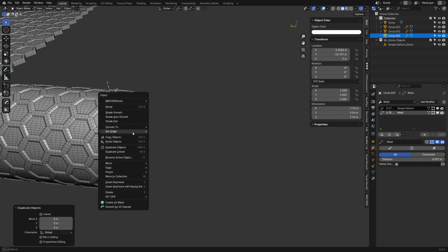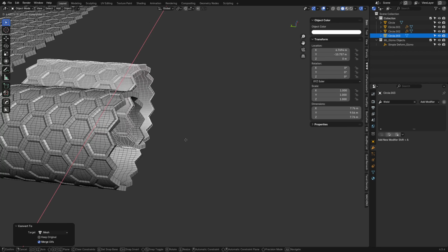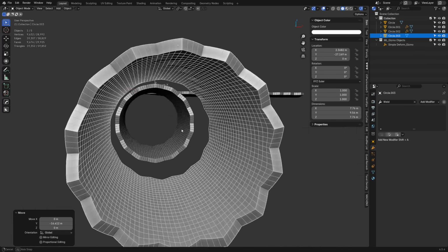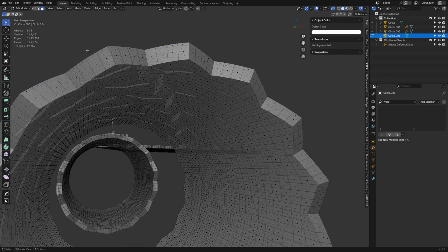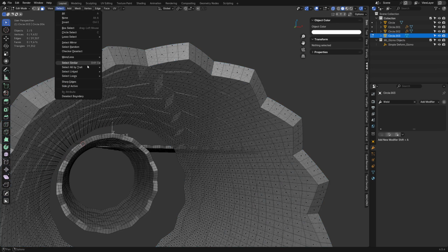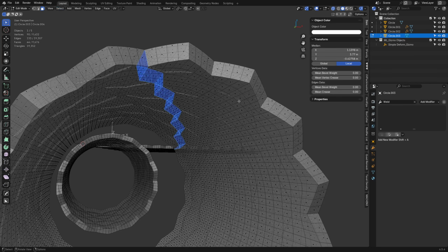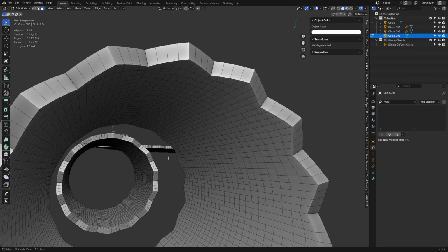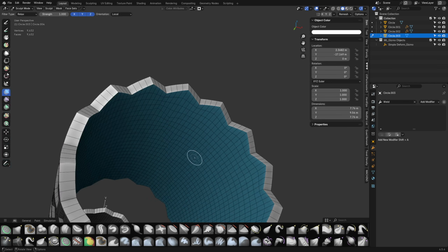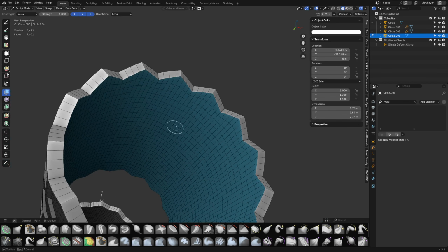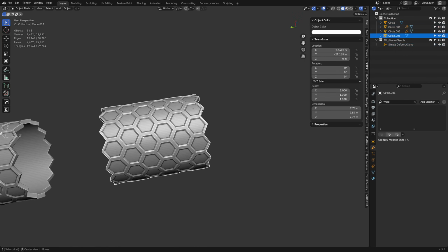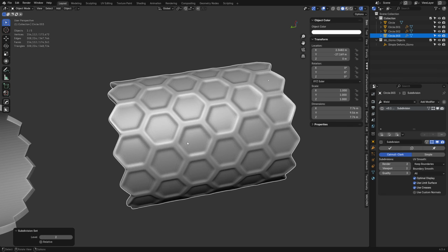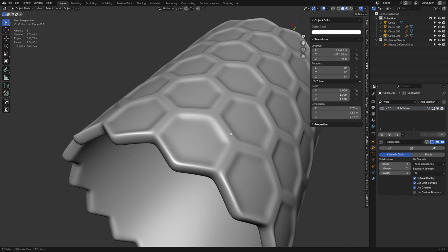I'm going to duplicate it, right click, convert to a mesh, Shift D to duplicate, right? We can go in here and we should be able to do the same thing where we select all by trait, interior faces, X, delete, that's gone. We can go to sculpt mode. We should still have a face set, so we can do another relax if need be. Okay. And so now we can subdivide this. We won't have any seams. It will actually fold back together the way it should.